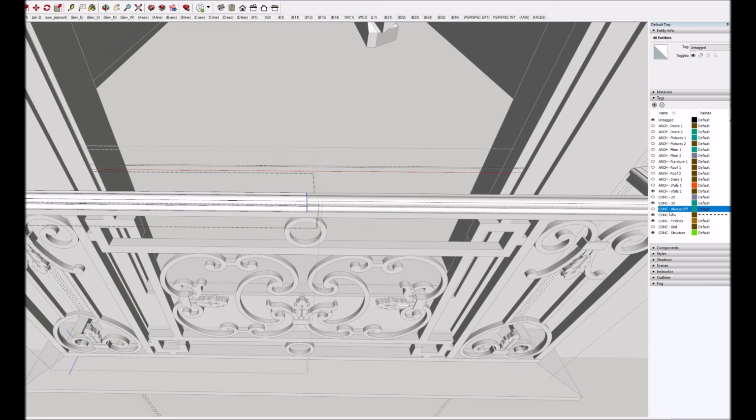And I should add that there's another way to do it. You can use the erase tool with Shift and that will hide the element. Hiding it works as well, but if it's something I think I might want to get at in the future, I find that it's convenient to have it on a layer and just toggle the layer on and off when I need it. So I'll move those things to always off, and they disappear.